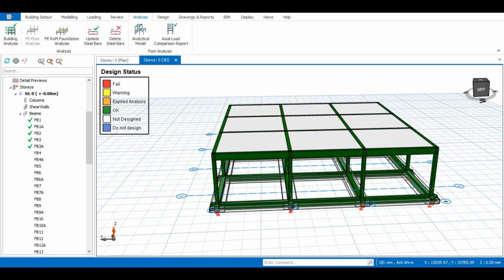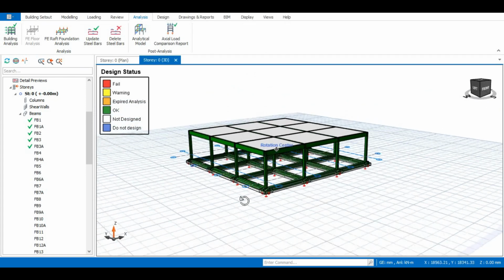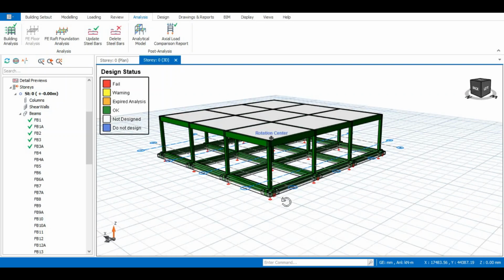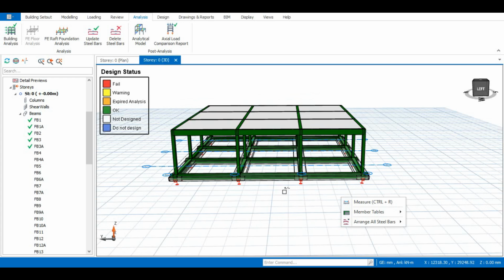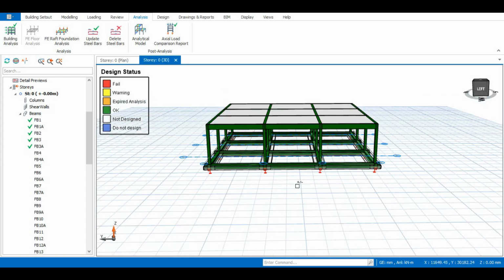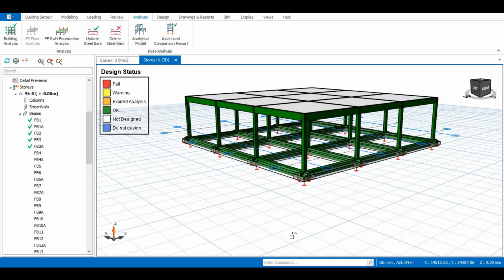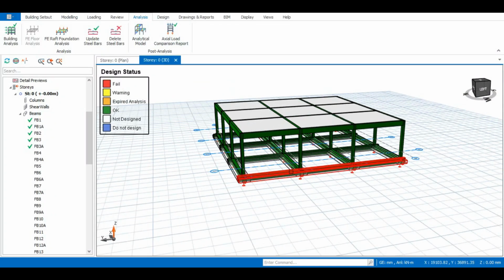And you should also know that the more complex your structure, the more complex your design, until at a point in time the foundation that is required for your structure is no longer a shallow foundation like this strip foundation. Because as far as we have, the soil stress for this model is 120 kilonewton per meter squared. Anything that is below that may not really work for this particular design, which means you have to design what works for it. This brings us to the end of our tutorial for today on how to analyze a strip foundation using the FE raft foundation analysis.